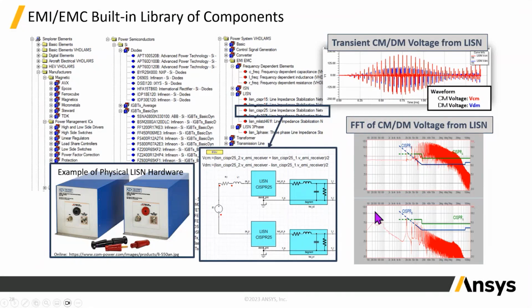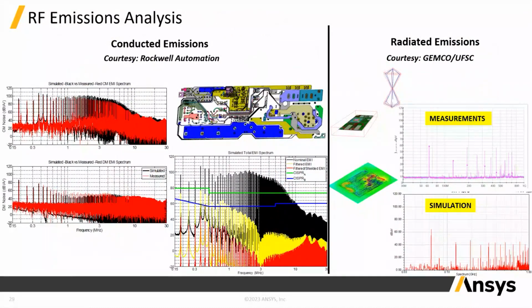It requires a lot of components because EMI/EMC involves PCB plus antennas plus cables, everything together. So to do EMI/EMC standards simulations, you need multiple components to model the complete electronic device. That requires LISN and a lot of testing antennas and waveform generators, and characterization of active devices. All these toolkits are available under HFSS or ADT, which you can use for conducted emission and radiated emission.